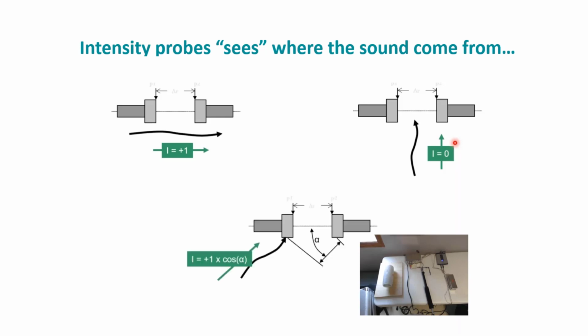most of that intensity. Lastly, if your microphone is off a little bit, you can start getting into some crazy math about how much intensity you'll actually be measuring. It'll be like a function of the angles depending on how you're holding it. So it's at like a 45-degree angle. So it's really important that you're holding the probe directly parallel to the noise source. If it's perpendicular or orthogonal, you're going to end up with 0 intensity, and that's going to affect your intensity measurement.